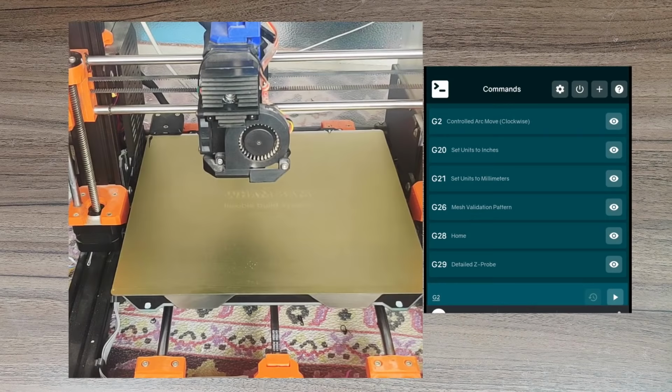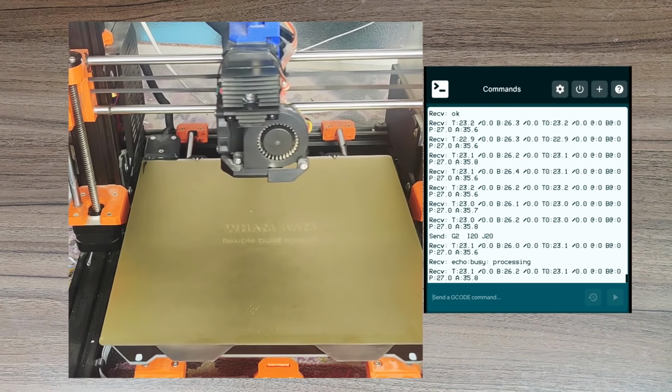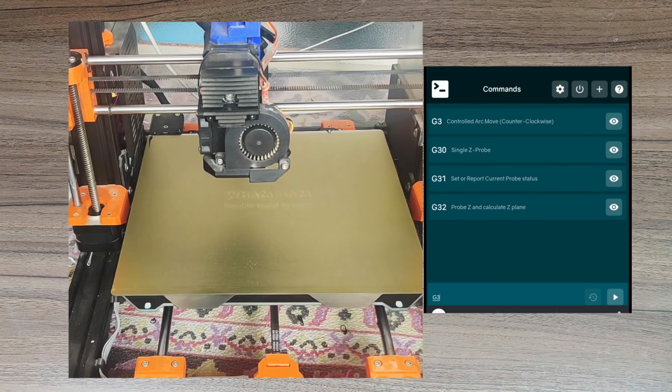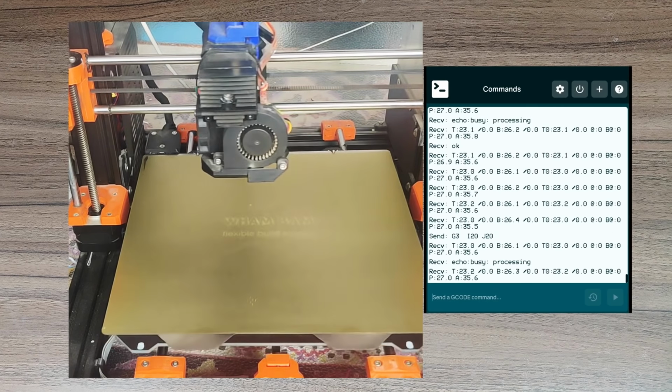There are a few other G-code commands that relate to forming shapes, such as the G2 or G3 commands that allow you to create arcs, or the G5 command that allows you to create a Bezier cubic spline. But they are almost never used. I don't know of a slicer that creates G-code with G3 and G5 commands in it. Even if you have to print a circle, it would be formed of many lines which are very minute in length, basically a lot of G1 commands. With enough lines, you can approximate almost any shape.